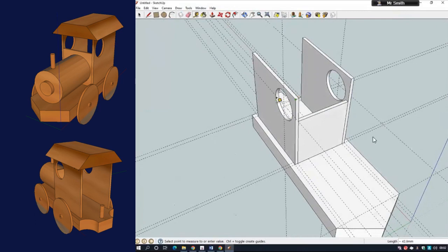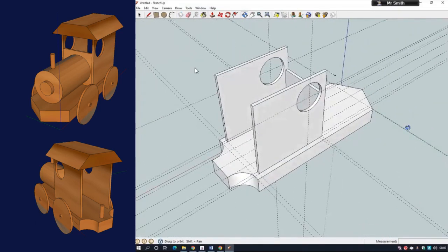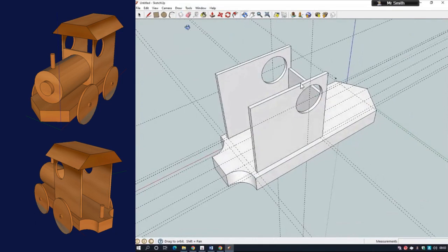I'm going to use a tape measure. So I want to do like a roof for it, but I don't want it to be directly in line. So green axis across, typed in 10. Do the same thing. So it's corner to corner, it's like opposite corners when you're drawing squares or rectangles. So I'm going to do the same thing over here. So you'll see the colour of it, which is green. And then green, that's this. Again, I've got typed in 10.